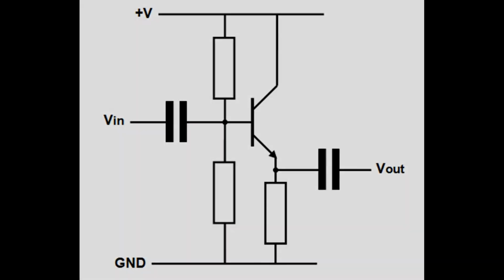Finally, have a look at this transistor circuit. Hopefully, you should be able to recognize that it has 2 high-pass filters, one on the input and one on the output. Without needing to fully understand this circuit, you should realize that it is blocking low frequencies but letting through high frequencies. Simple.